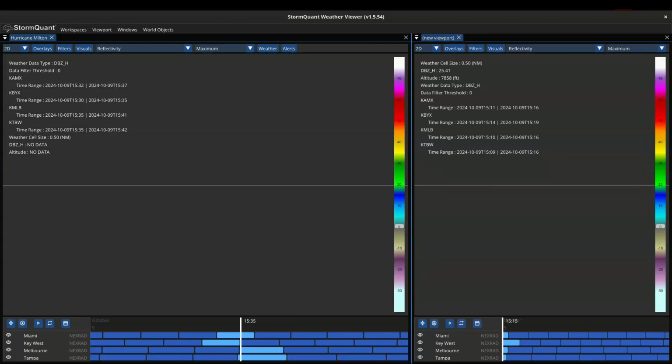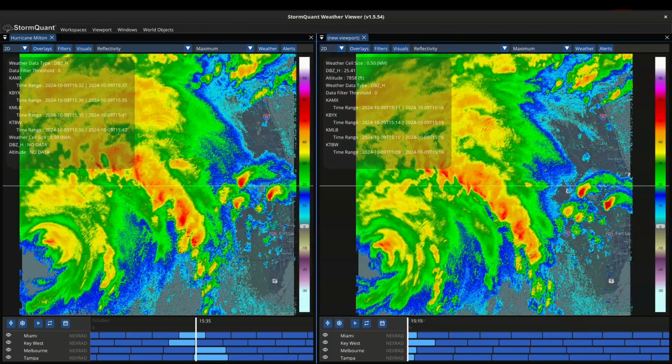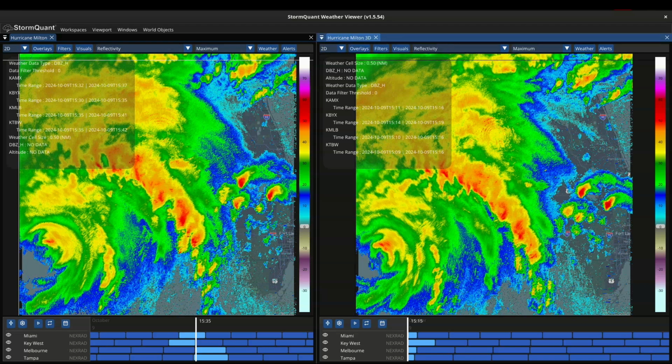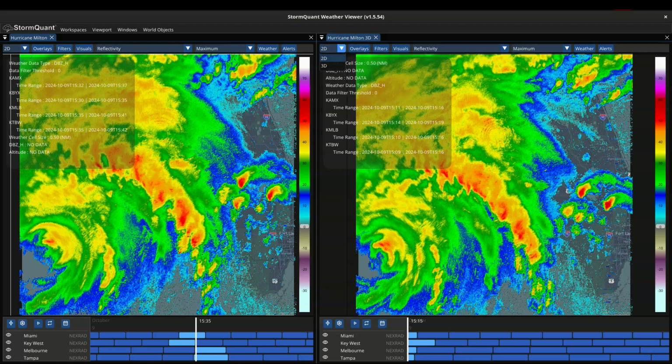You can then resize the viewport by left-clicking on the dividing line between the viewports and dragging. This simultaneously adjusts neighboring viewports. Each viewport has a nameplate at the top. Change the name by right-clicking in the box, then typing the new name in the pop-up window. Select Close when complete.